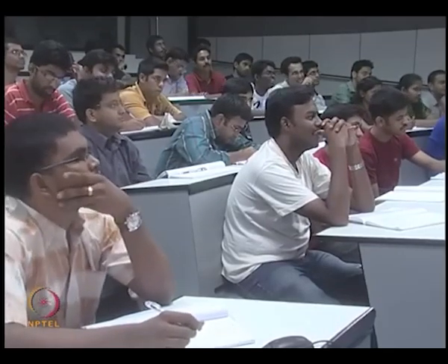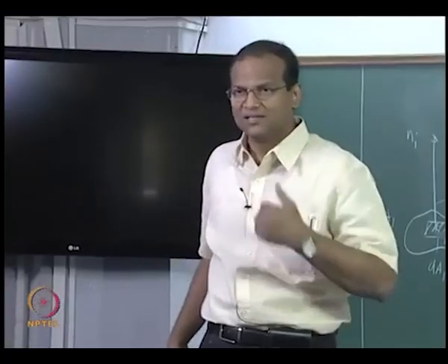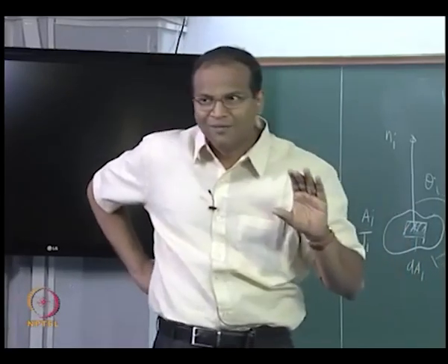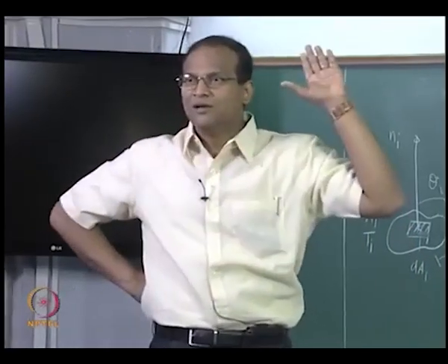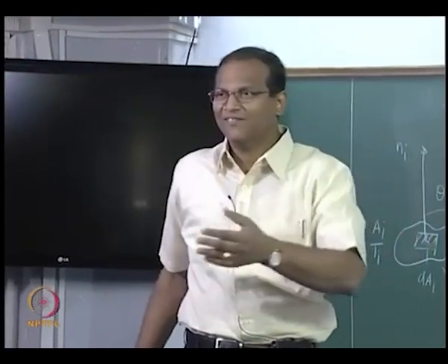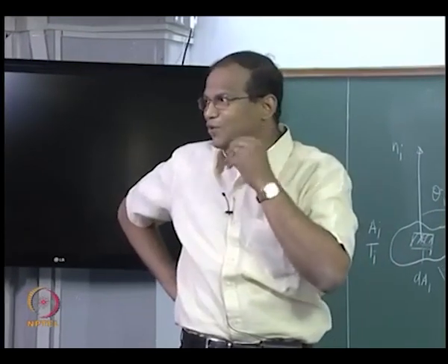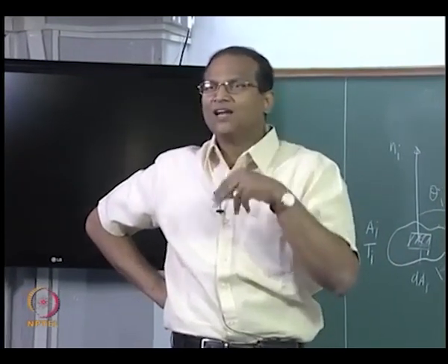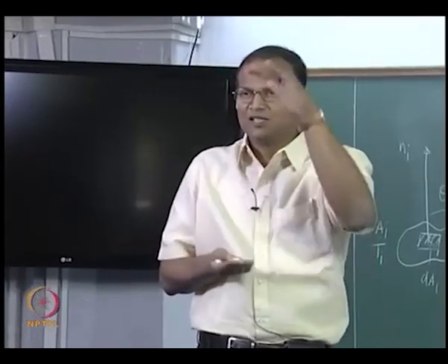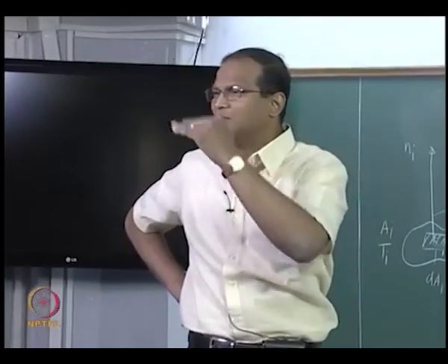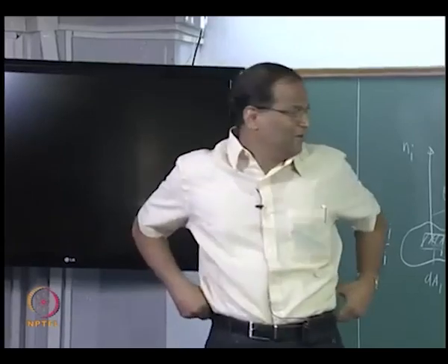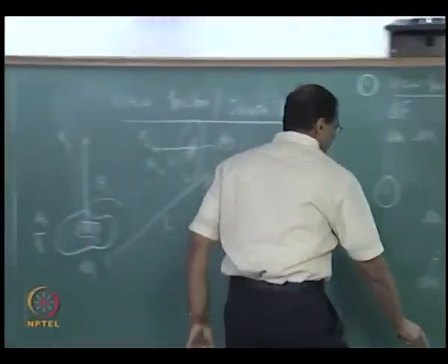So, Sparrow and his colleagues, after doing all this, developed a technique called contour integration. Contour integration is a special craft known only to radiation heat transfer people, because to break down this quadruple integral, it is more than a triple integral. Fortunately for us, these integrals have been solved and are available in the form of charts: simple cylindrical disc to disc, parallelogram shaped surface to rectangular surfaces, cuboidal surfaces, perpendicular surfaces and so on, okay. Now, this is the view factor for a uniform radiosity.